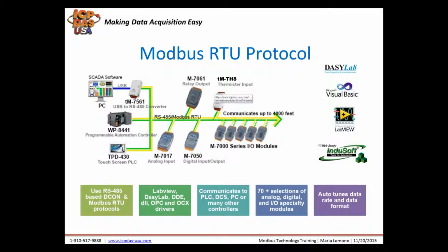Modbus is a serial-based communications protocol that's widely used, and it supports up to 255 devices in one network. It's openly published and royalty-free. It's easy to deploy and maintain. It supports communication distances up to 4,000 feet and can communicate further with repeaters like our i7510 products.